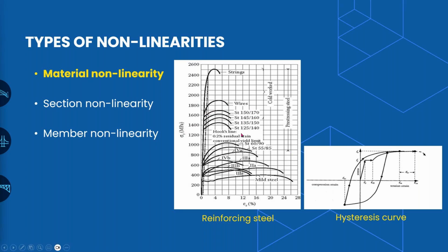Depending upon the grade of steel, the wires which are generally used in cable-stayed bridges have very high strength and very low ductility, and hence they will be susceptible to breakage, and we need to check for that as well.